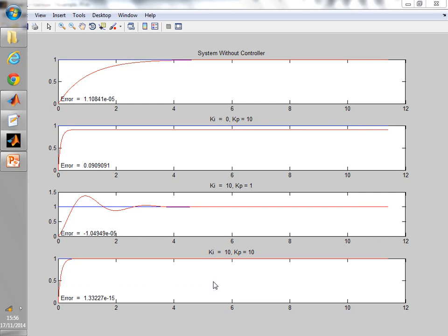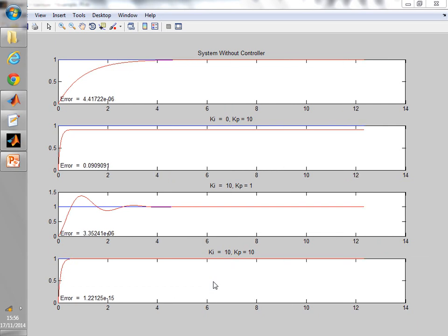If I want to improve both steady state error and fast response, the lowest value for the rising time, the Kp and Ki equal to 10 is enough. Now let's look at another type of the input.